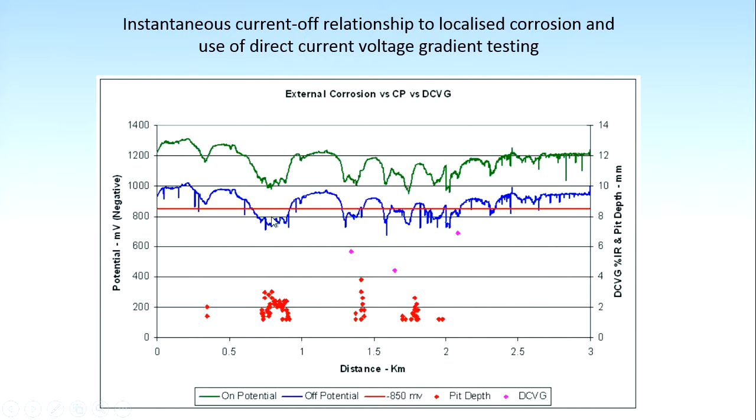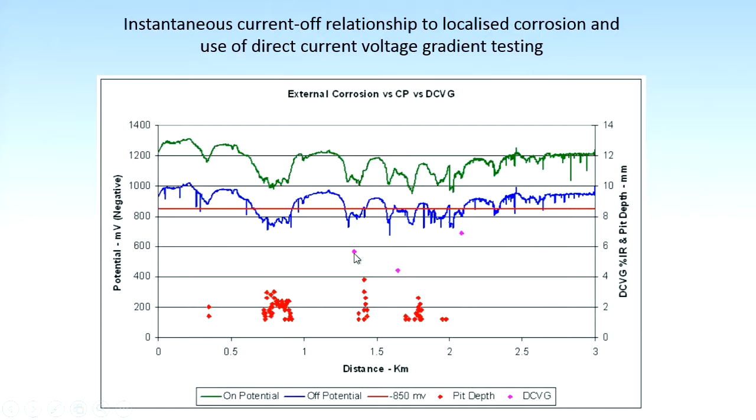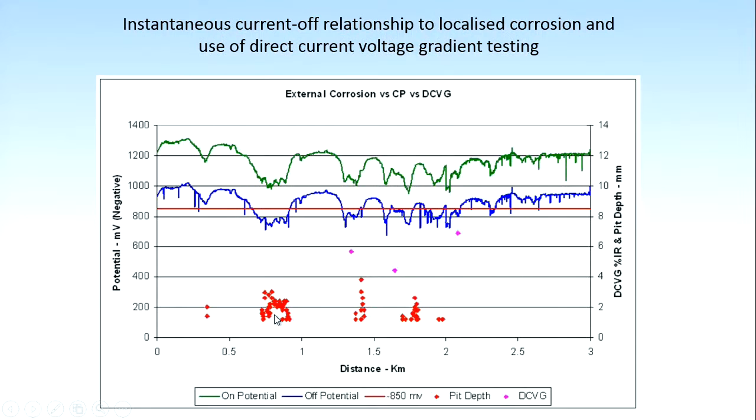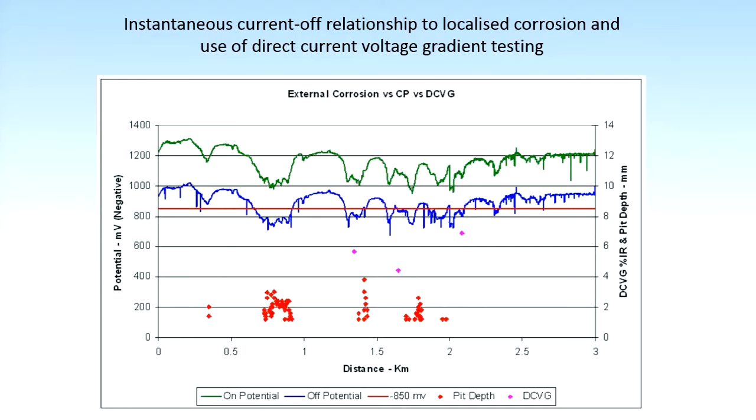And this is part of the problem with taking the measurement at a particular time, because the soil resistivity changes with the seasons. There are other factors, stray currents and things, influencing the data. And so, in fact, what you want to do is surveys at a regular interval, so you can pick up what's really happening against the noise, against the seasonal variation and the interferences that are happening. Of course, there's no substitute for actually looking at the pipe itself, but that's not easily done in a lot of situations, and you don't want to just start disturbing or digging into coatings necessarily. Okay. So that's actual data.